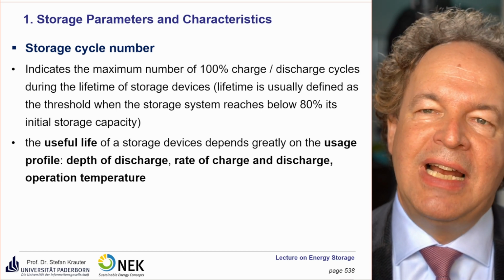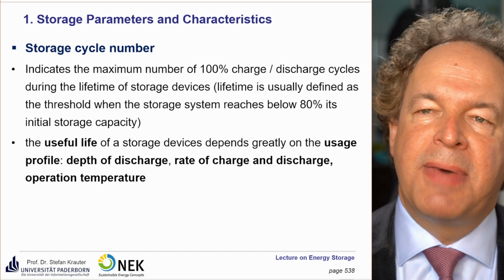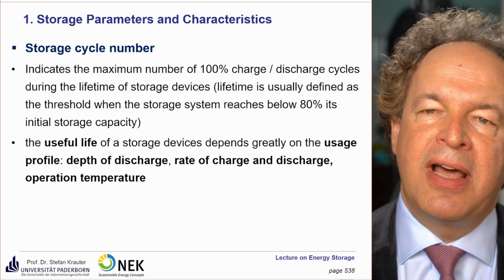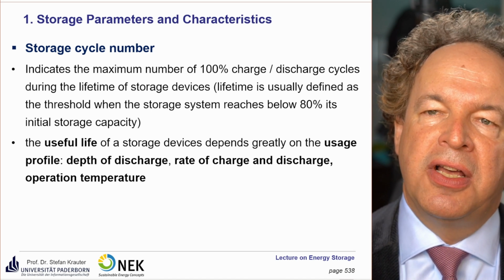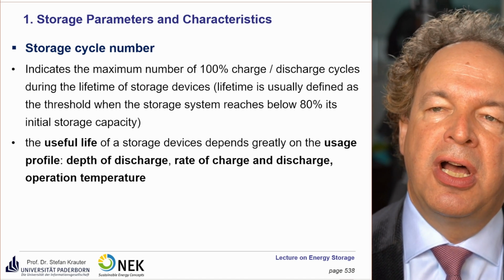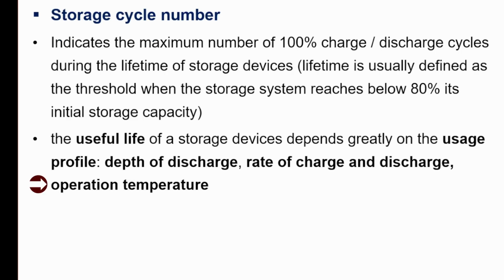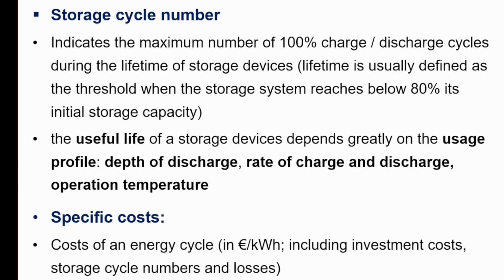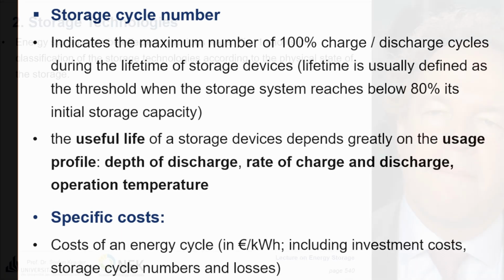The useful life of a storage device depends greatly on the usage profile, the depth of discharge, the rate of charge and discharge, and very important, operation temperature. Then the specific costs: we have the costs of each energy cycle expressed in euro per kilowatt hour or euro per megawatt hour, including the investment costs, storage cycle numbers and losses.